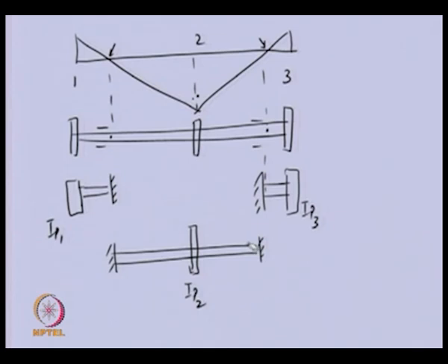at present they are unknown, the node position is unknown. So, if we know that, we can obtain the natural frequency of this system, and this system, and because we have broken them from an original system, the natural frequency of all these 3 systems should be the same and should be equal to the original system. So, this is the basic idea by which we can obtain the natural frequency of the original system.